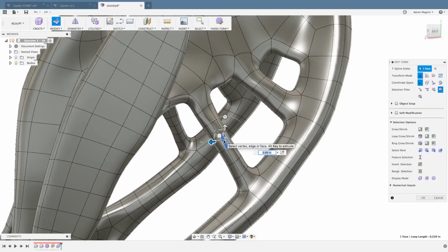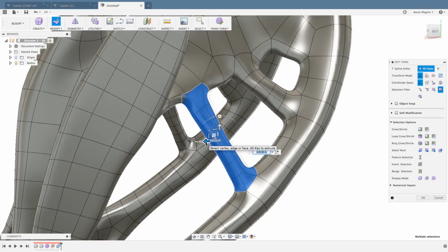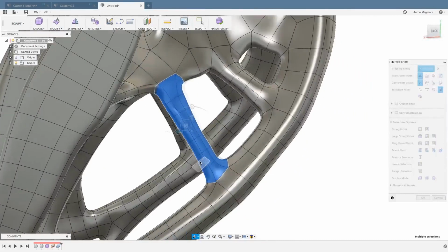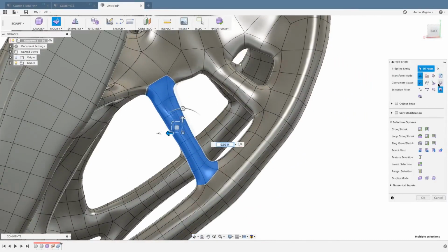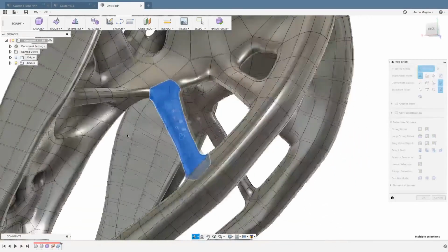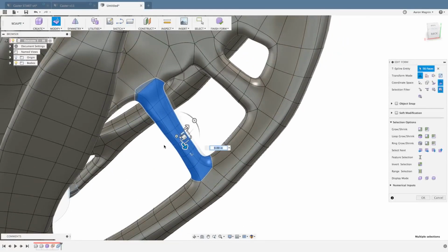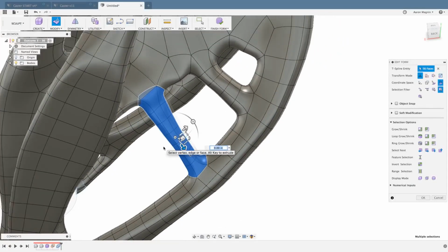Essentially, I'm just going to select a face, and then I'm going to hit Control H. It should select that whole strut, and now I can start sliding this around. As mentioned in our What's New video, this triad orientation isn't really that great for what we've selected there. So there's a new option to adjust the coordinate space per the entity. If I select that, it actually adjusts that triad, so it's going to enable me to adjust this maybe along the axis. Some very nice things about that.